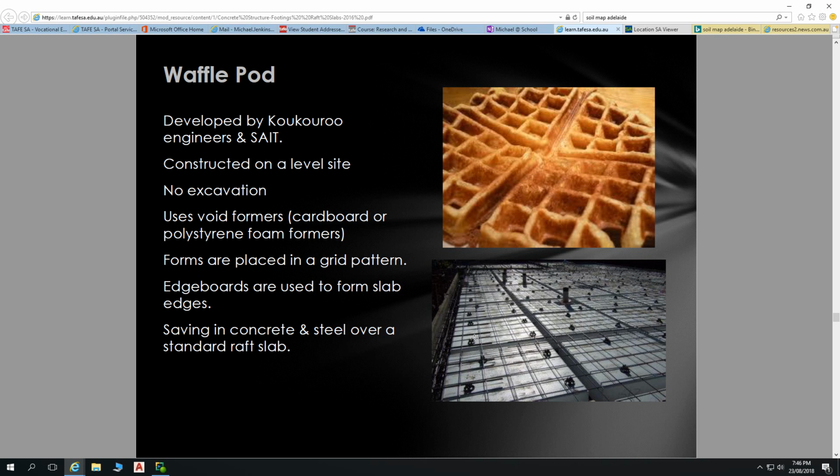So as I said before, you set it out on a completely flat site, and then put your pod lock spacers in there, your reinforcing bars, plastic chairs with your mesh, your edge formwork, and then you're ready to go.